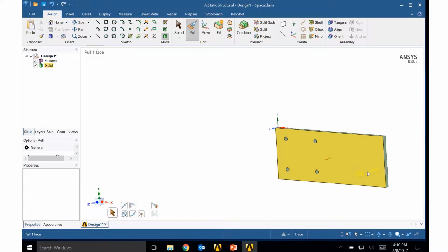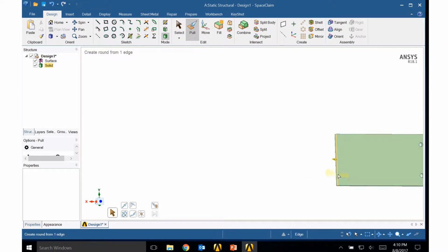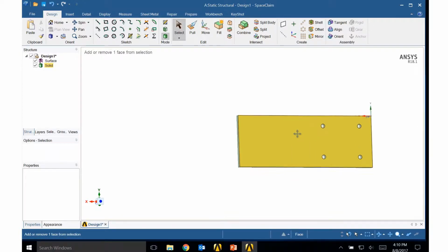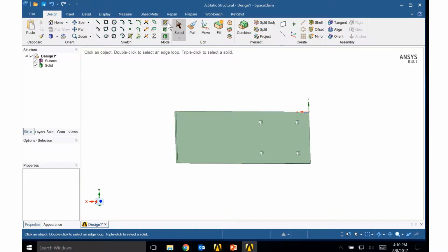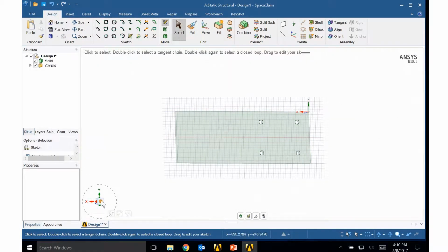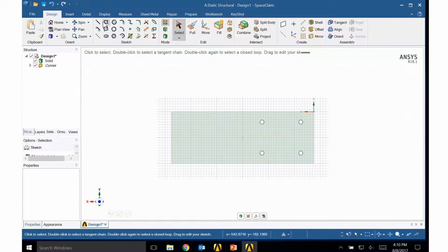I'm ready to build the vertical support. So I'll escape out of pull mode. I'll rotate this around, and I should have escaped one more time. Then I'll control middle mouse button and drag. I'll click on sketch mode and select that sketch plane, and I'll look at it directly in the Z-axis. I'll come to rectangle, and I will start this rectangle